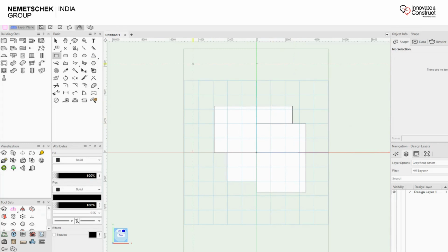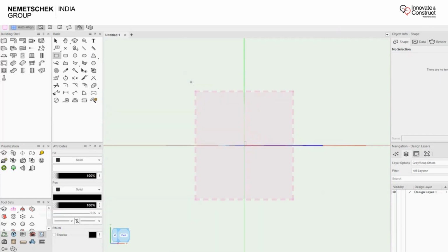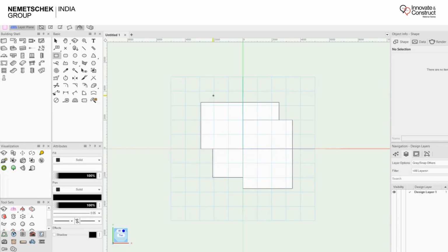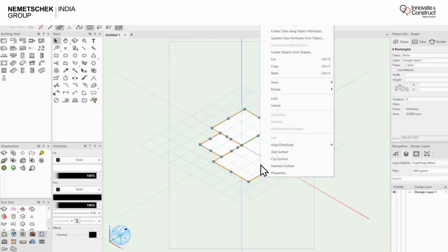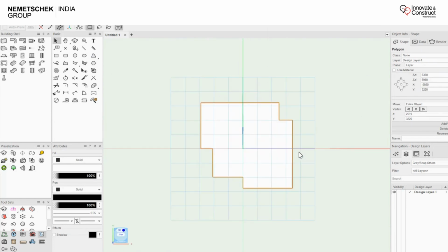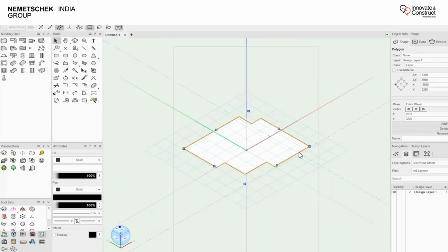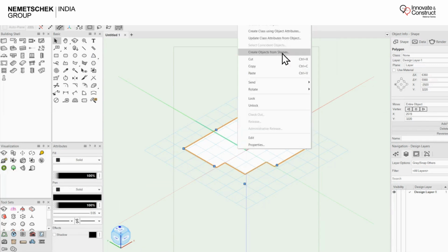Once everything is defined, I can quickly visualize it in 3D. Okay, this is my form that I created, or maybe I can say this is my cafeteria, whatever I'm imagining. Once you're done with that, I can add to a surface. It will quickly add back your surface. Your overall surfaces have been added, or you can build all sides of the wall from there as well. But I'm just showing that at the moment for the external walls only.